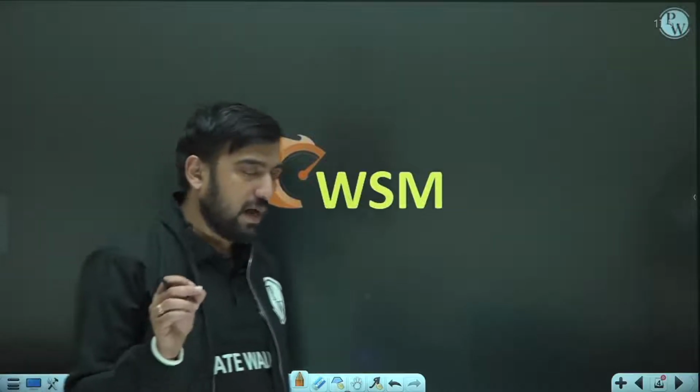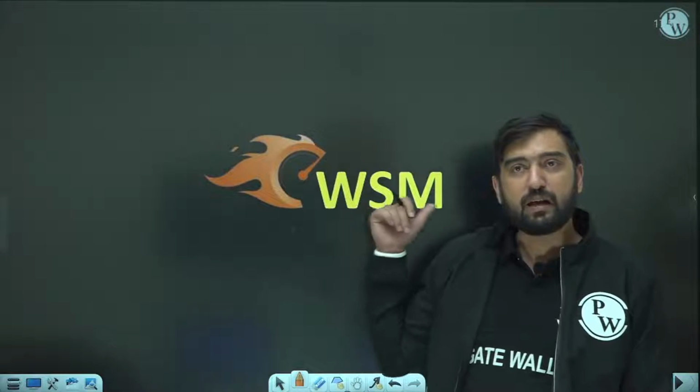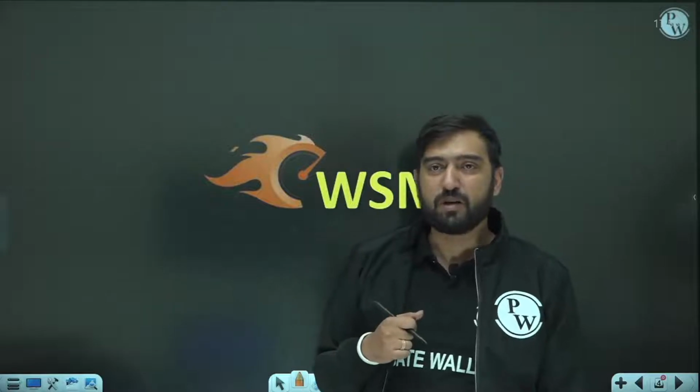As I told you, in RCC broadly three design philosophies are used. One is WSM, and the other two are LSM and ULM, the ultimate load method. We have studied our entire course based on the limit state method. What is the basic difference between LSM and WSM? I covered the same in my lecture number 2, but let me tell you one more time: in the working stress method we ensure the safety of our structure only by underestimating our material, whereas in the limit state method we underestimate our material as well as overestimate our load. Are you getting it or not?